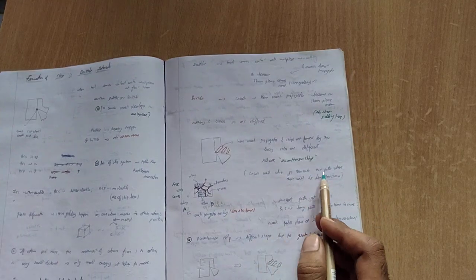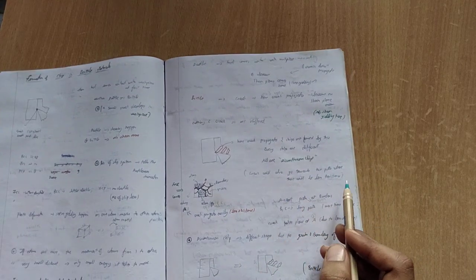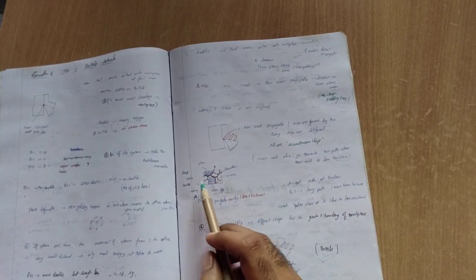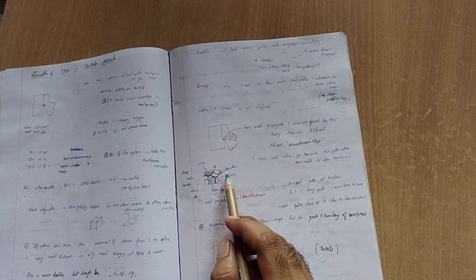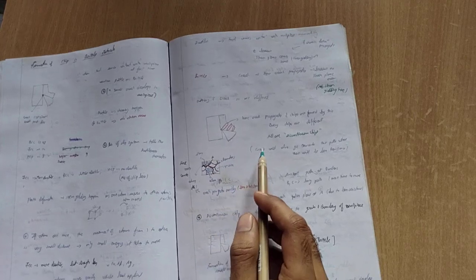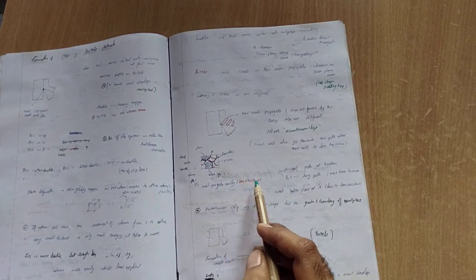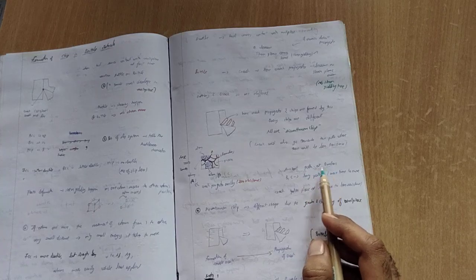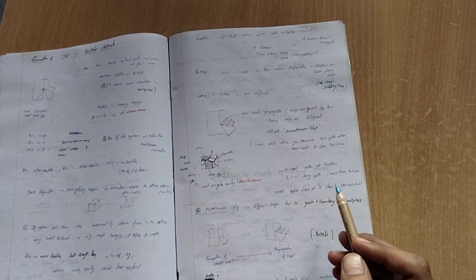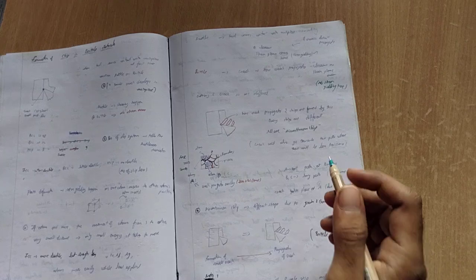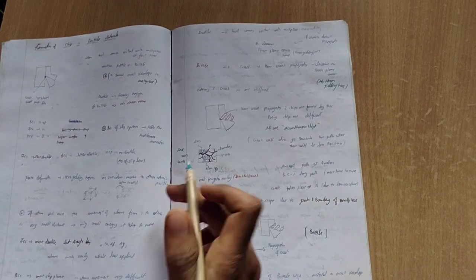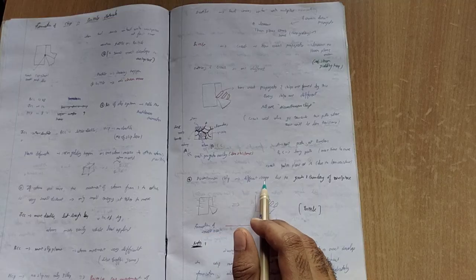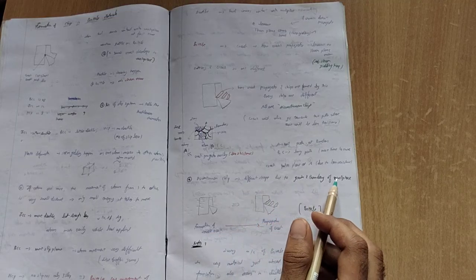The crack will also go towards the path where the least resistance is. So this is the material: when force is applied, the atoms, different boundaries and the grains are different. So the crack propagates easily, with less resistance. You can see A is a short path at the boundaries and B is a long path. So B and C require more time. Whenever there is a short path, it can discontinue there. So discontinuation gives different shapes due to the grains and boundaries of the workpiece.